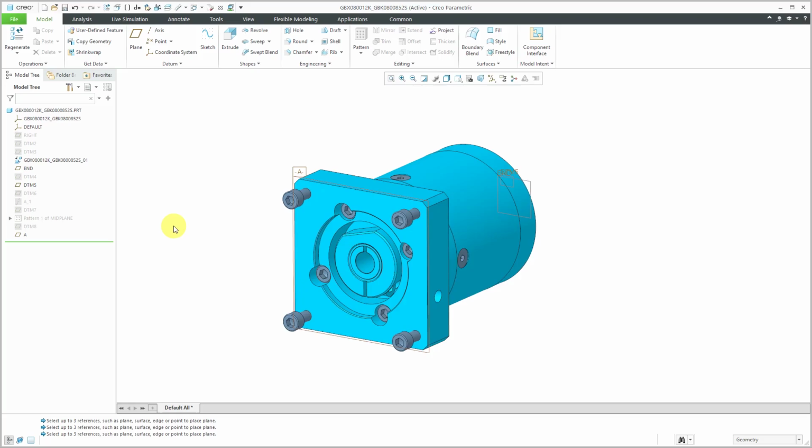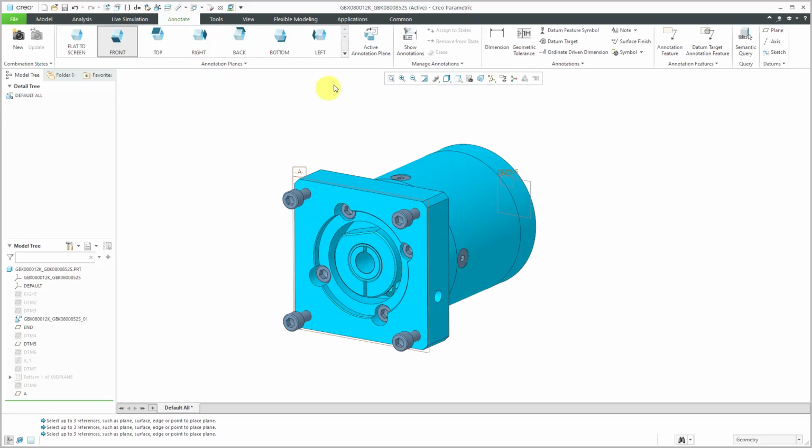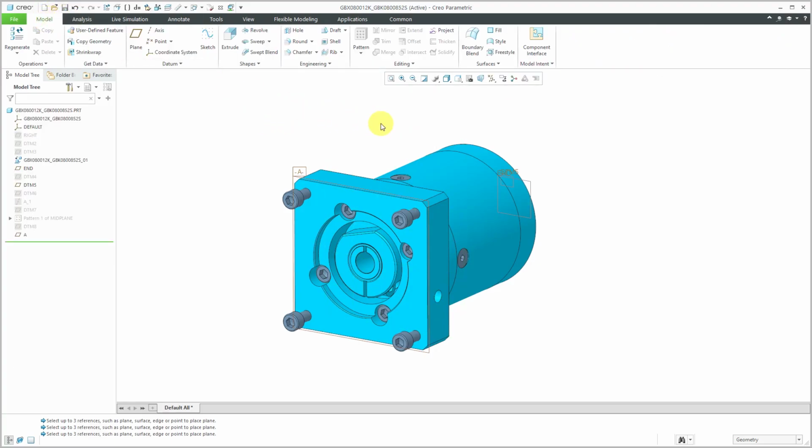And there was another one that came out in 2018. Actually, it's the 2018 standard, but it was released in January of 2019. But again, this is the old style. You should not be doing this. And if you have any of the old set datums in your model, you should use the conversion tools from Annotation tab, Annotations Overflow, Legacy Datum Annotations Conversion, in order to update them to the 2009 standard.